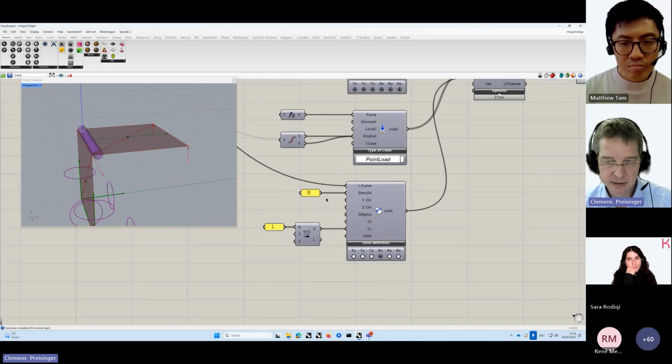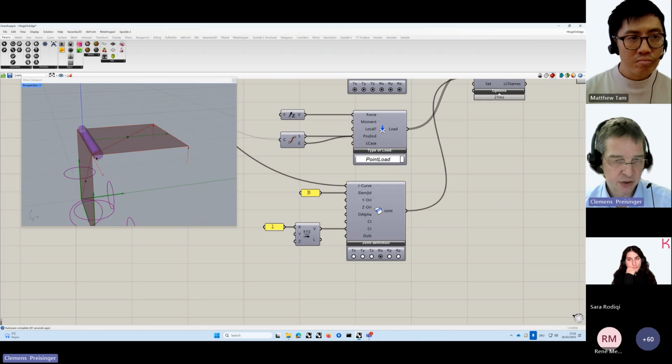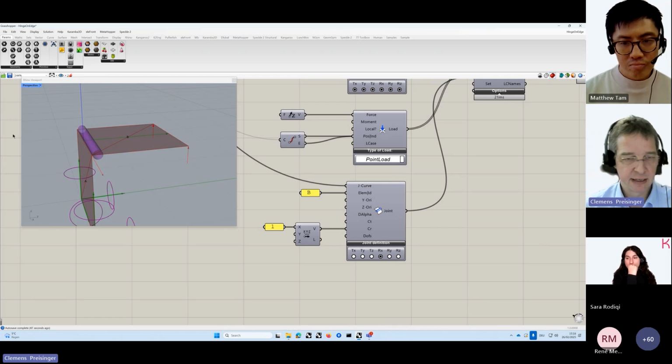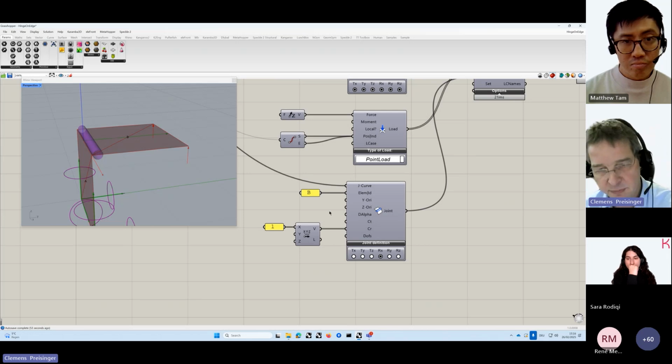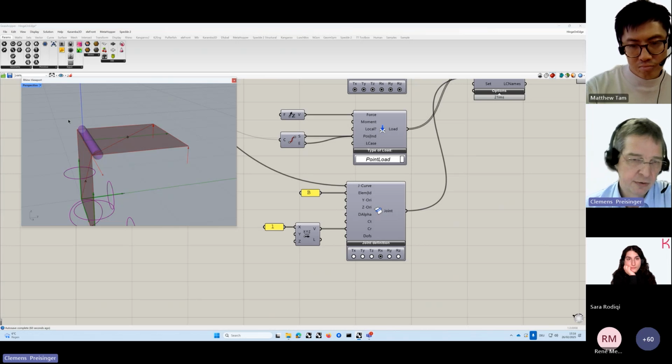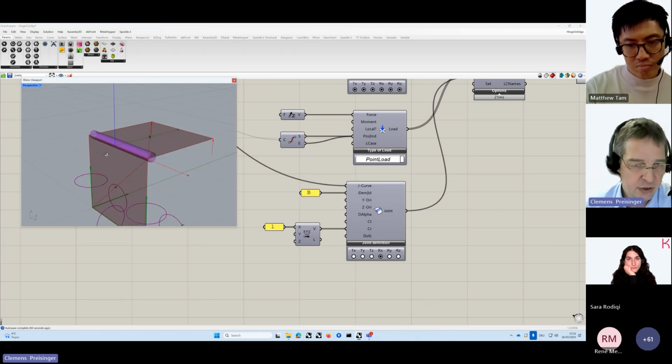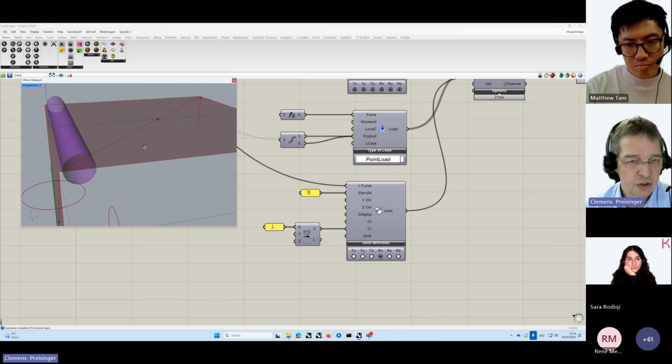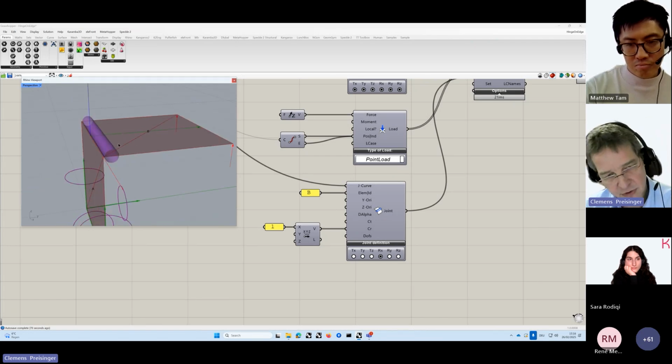But in that case, since this here is a naked edge of the shell patch B, it's automatically detected by Karamba, and you do not have to specify any directions here, which is quite useful, especially if you have more complex geometries where it's hard to define the direction towards the surface where the line joint shall lie. And also we improved the rendering of the line joint, so now it's very clear on which side of the line, so on which surface this line joint actually lies.